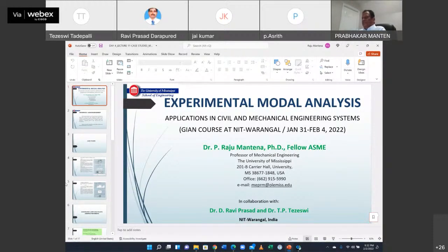But typically, it's the modal pattern which does have curves associated with it, yes. Whereas an operating deflection shape need not have perfect curves like that. It is some sort of a general disturbance and movement of the overall structure. That is the closest explanation I can give you for the two different concepts.